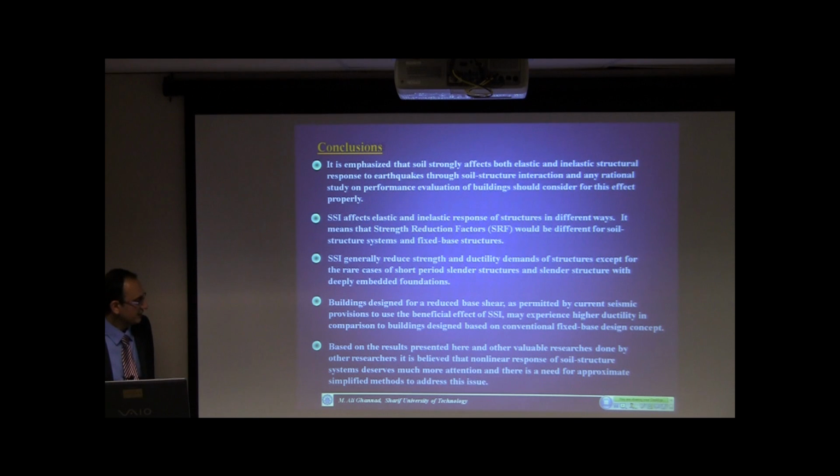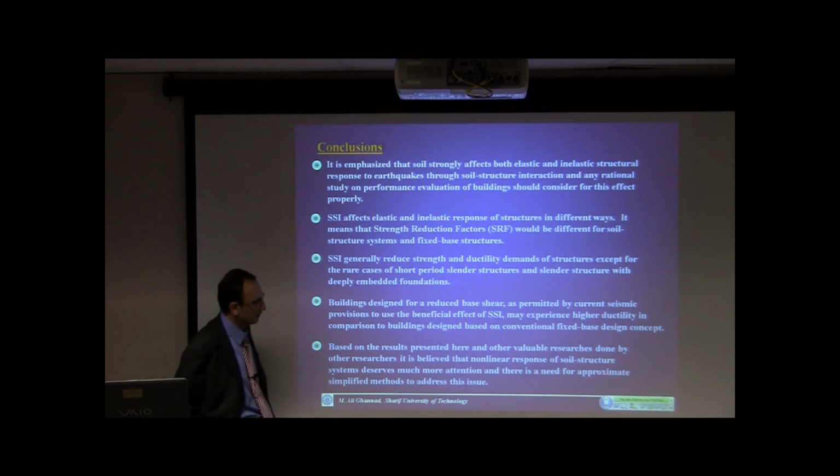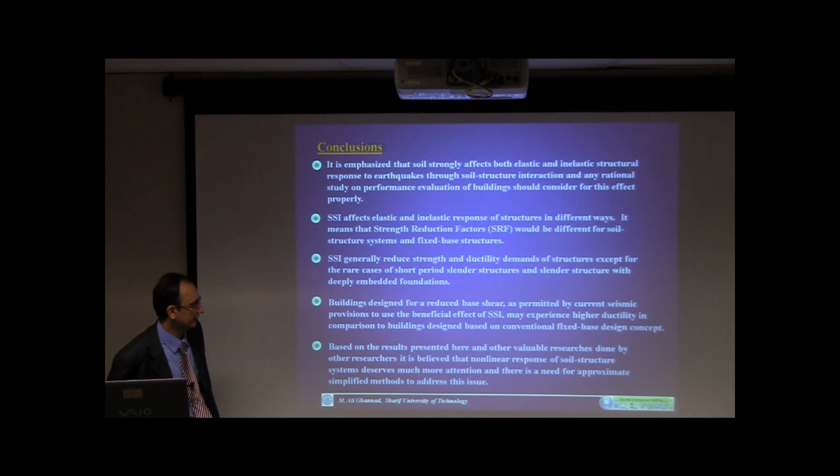And buildings designed for a reduced base shear, as permitted by current seismic provisions to use the beneficial effect of soil-structure interaction, may experience higher ductility in comparison to buildings designed based on the conventional fixed-base design concept.